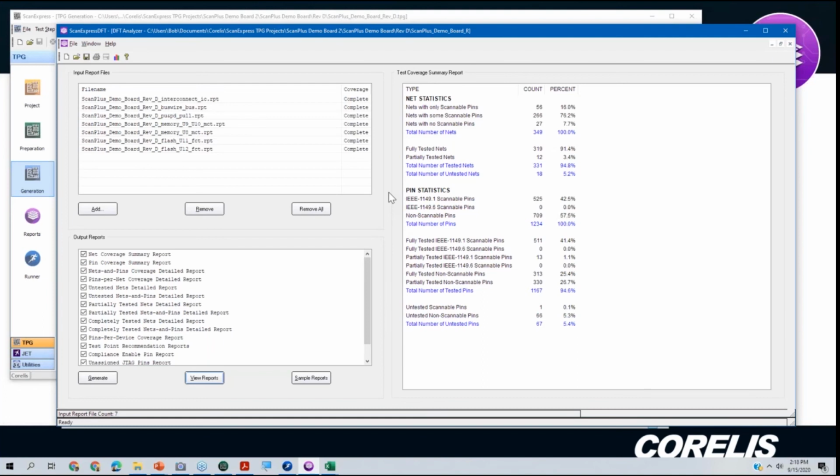I know many of us work on designs that have a mixture of analog and digital. Boundary scan is generally only going to get you digital coverage. Sometimes we can make analog things happen by controlling digital nets, for example, with a DAC, but otherwise, we do need separate coverage for analog and digital. We do have customers though that make highly analog products, but they do have a digital subsystem with a DSP and a CPU, maybe some memory, and they are able to get some coverage from boundary scan to make sure that those subsystems are working correctly, or at least structurally correct prior to going on to functional test.